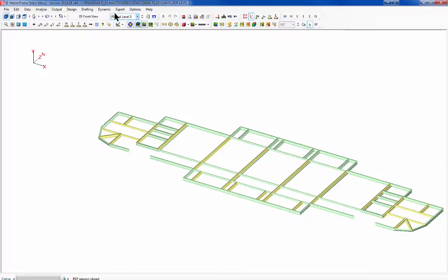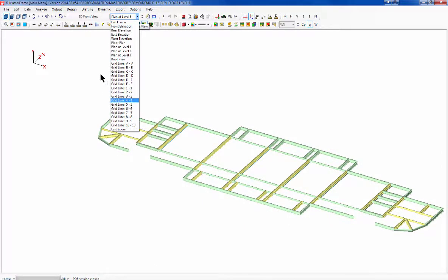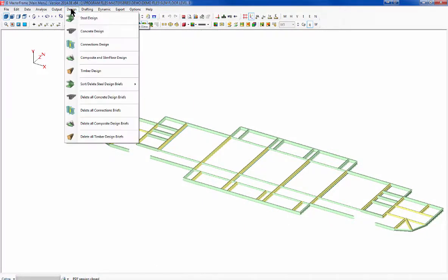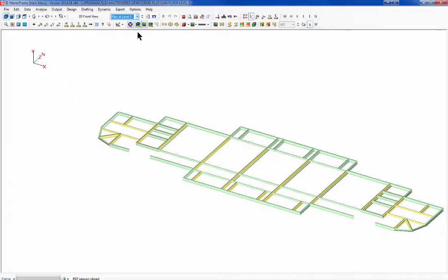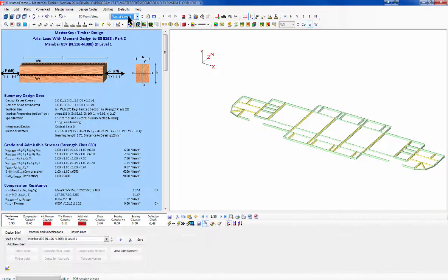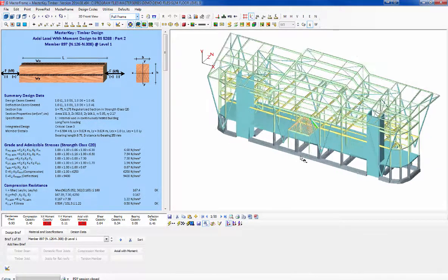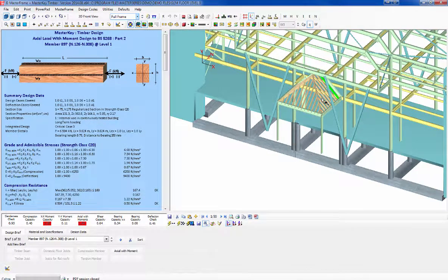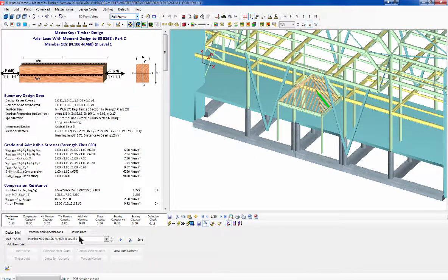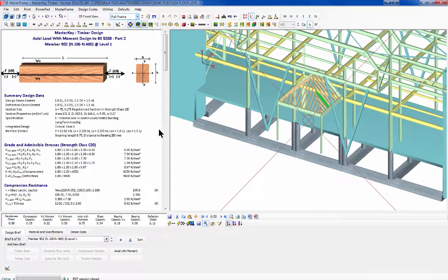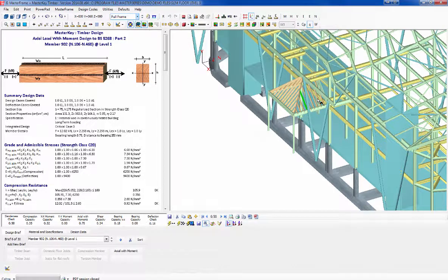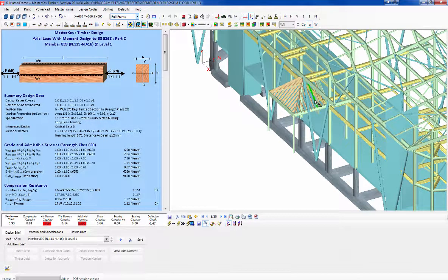And finally, in the design components, timber. Not much to say about timber. If I go to full frame and I just choose one of these timber rafters, we'll see that it works. And obviously you would not think of cutting it down to be smaller for each rafter, so we will just stick with the one.